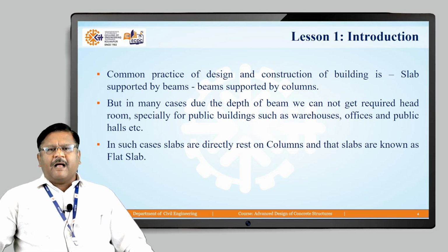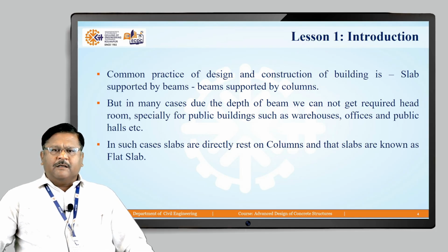But in many cases, due to the depth of the beam, we cannot get the required height or clear headroom, specifically for public buildings such as warehouses, offices, public halls, etc. In such cases, the slabs rest directly on the columns, and such slabs are known as flat slabs. So we eliminate the element of beam.